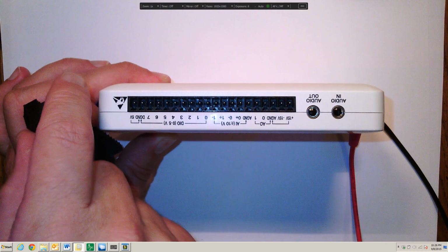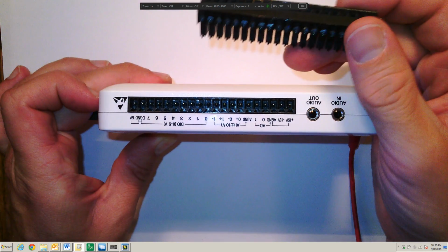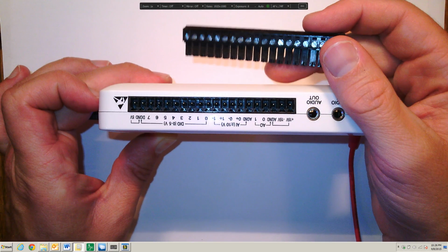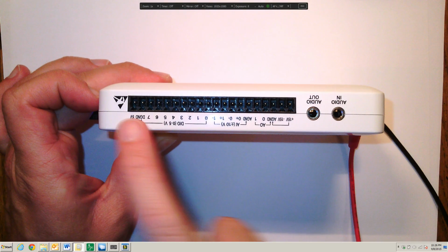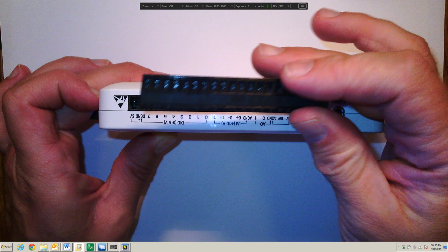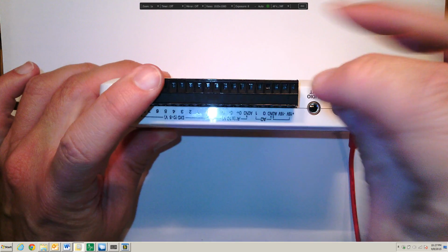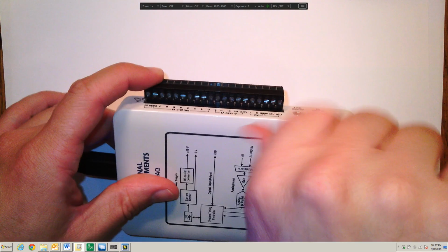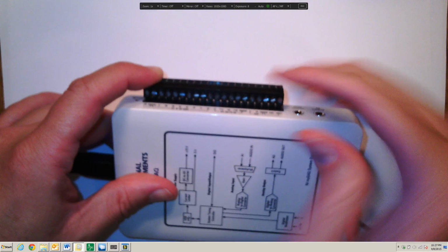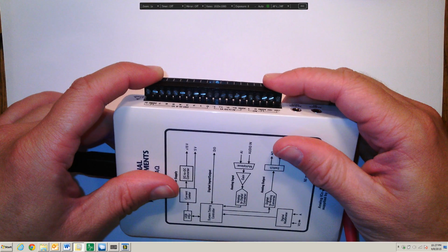Finally, I should point out that with the National Instruments device, there comes this terminal strip, and what this is meant to do is slide over the pins of the different analog and digital outputs so that you can access those, and you can easily put a wire into these terminals and screw that wire down, so you have easy access to readily connect your MyDAQ inputs and outputs, at least on this side of the device, to a breadboard circuit.